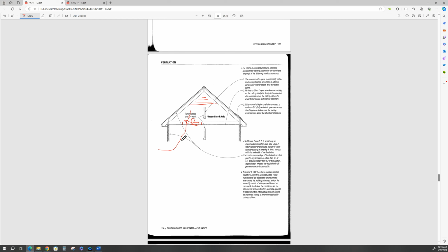It's a great way of taking the ambient temperature out here and exchanging the air in a residence very quickly. And then you can turn it off once the temperature in here equals the temperature outside, and then turn your HVAC back on.